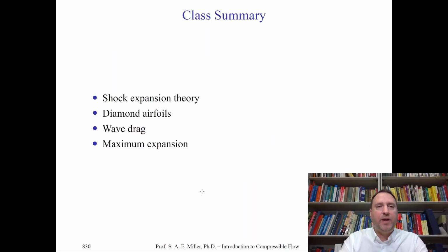In this class, we introduced the idea of shock expansion theory, which is nothing less than combining the ideas of oblique shock waves with Prandtl-Meyer expansion theory. We then applied that directly to the most classic problem of the diamond airfoil. We then looked at an example of a flat plate airfoil, and then looked at the particular wave drag, which is the integration of static pressure over the airfoil. Remember, wave lift and drag are the dominant forces at moderate supersonic speeds for these problems.